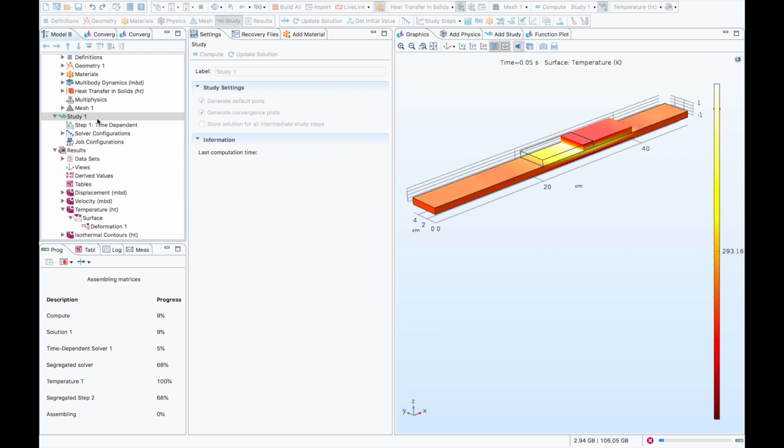And then I will go on with some multiphysics options here that you can run. So now you can see, because we apply the sine function, the upper block is moving, and we have some temperature change as the friction generates heat between the two bodies. Okay, if you need more precision, of course, you can change back to quadratic elements, but for speeding up the computation, I use these linear elements here.